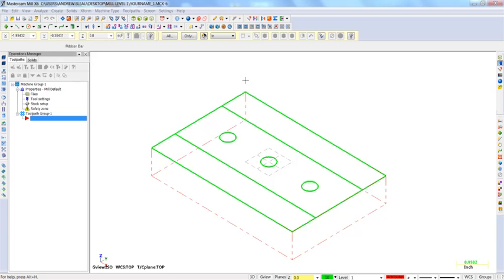At this point, we will start machining the part. We will machine the two steps using a contour toolpath. A contour toolpath removes material following a path of curves. Contour toolpaths only follow a chain and they do not clean out an enclosed area.